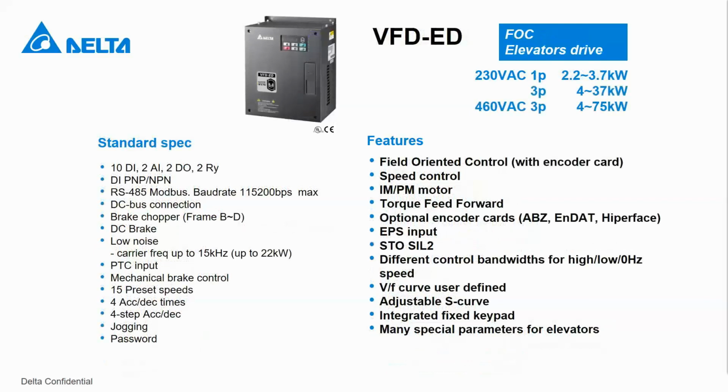Finally, the last drive that I would like to show in this presentation is the VFD ED drive. This is made for elevator applications, so you can find some typical functions for elevators, such as EPS input. That means that you can connect a UPS to the drive for emergency rescue operations.